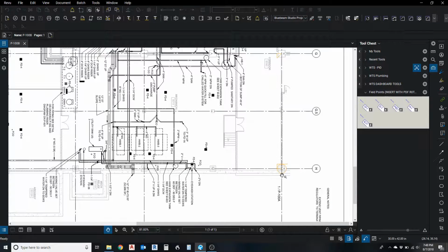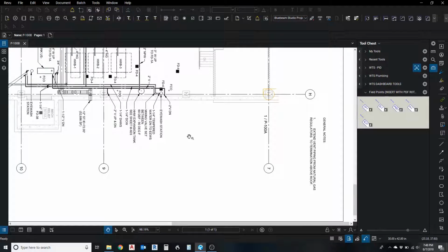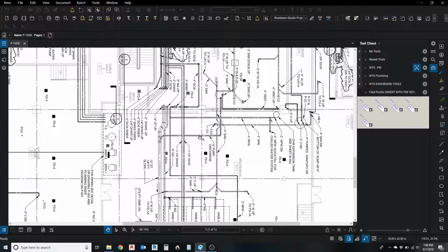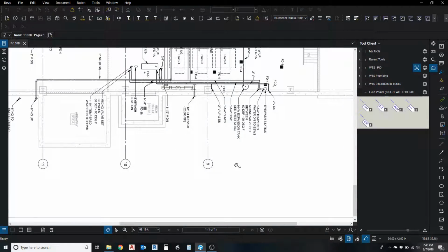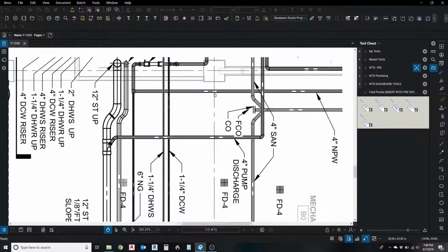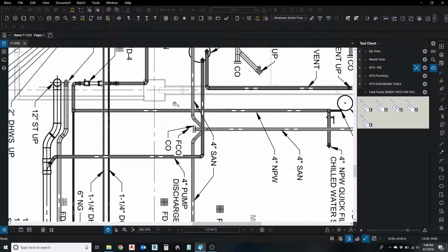And you're going to tell him to do that for, say, H7, and you're going to tell him to do this over at like a G6, and he's going to do that. And I would say tell him to do these points at 5 or 6 locations and then report back to you that they're done. And what this is going to allow us to do is we're going to replicate those points here with our control file.